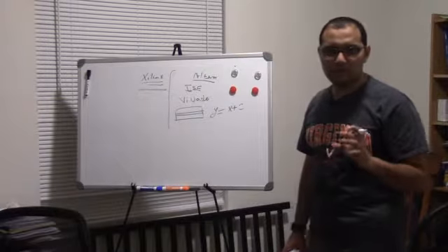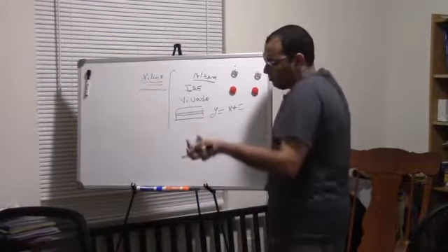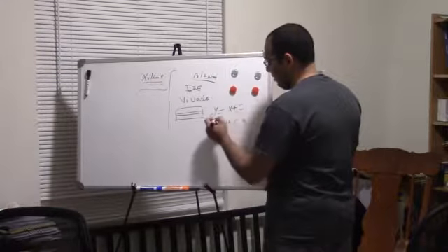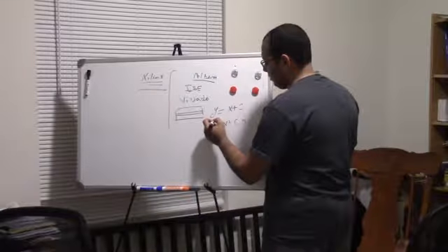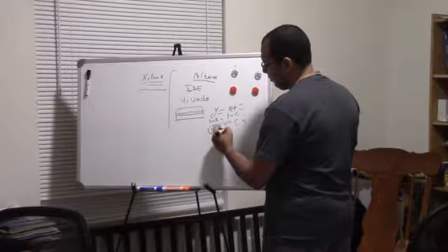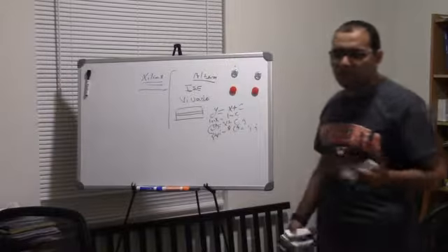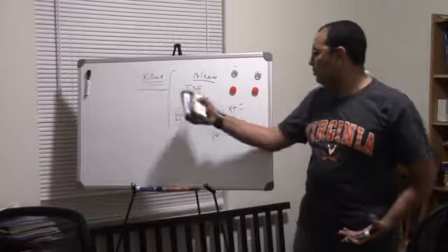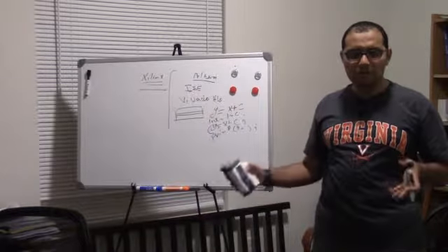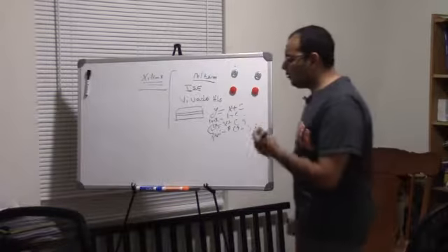I can describe it using a high-level language, for instance C. I would just say y is equal to x plus c, and then I will declare int x and int c or whatever, and then I will say printf y, maybe as a decimal or whatever. Then the tool, Vivado HLS, high-level synthesis, will convert that into the hardware language Verilog or VHDL.